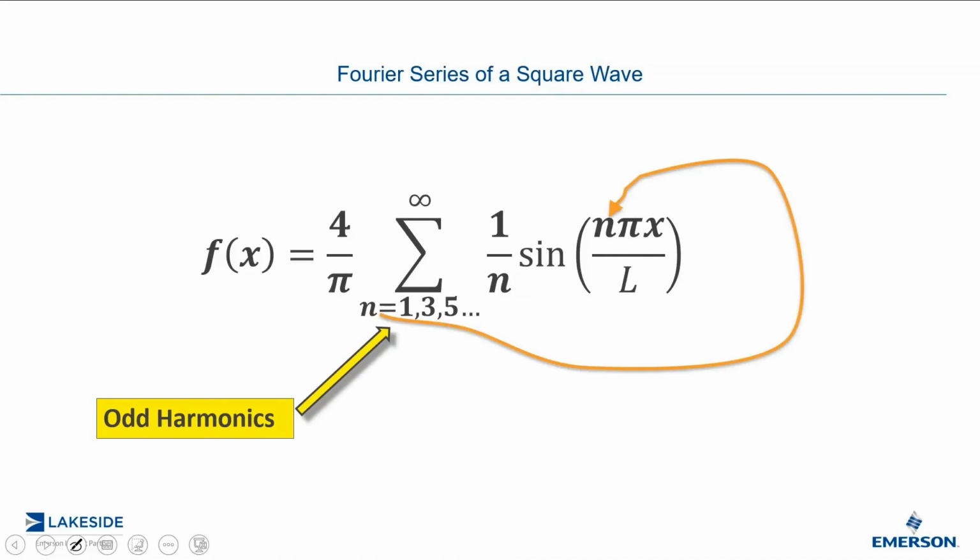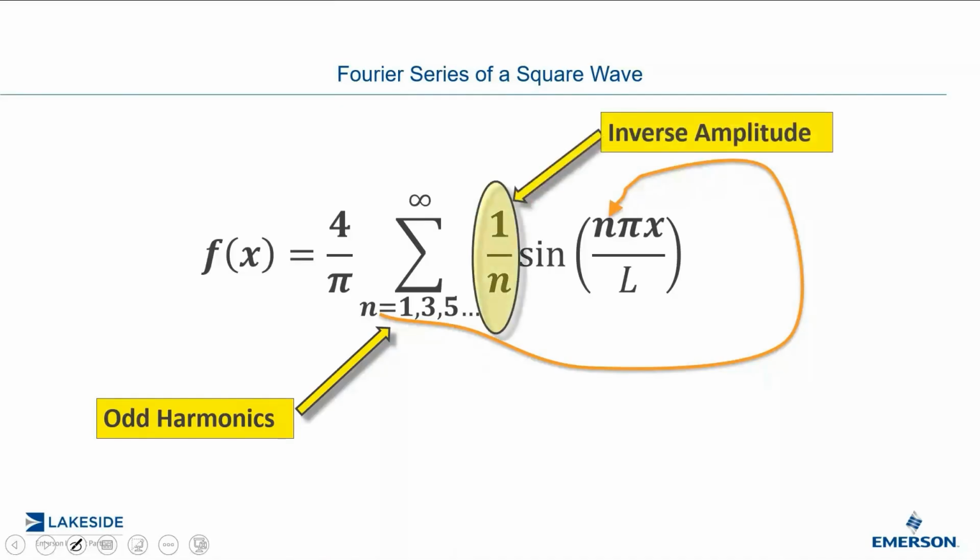It's different for a triangular wave and so forth, but for a square wave, you use the odd harmonics. So you've got your base harmonic at 1, and then three times faster for the second harmonic, 5 times, 7 times, 9 times, and so forth. And not only that, you would take the inverse of the amplitude. If you add up all those harmonics infinitely, you would reproduce a square wave.